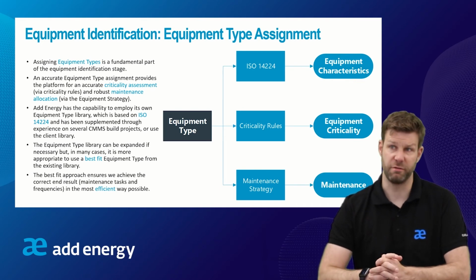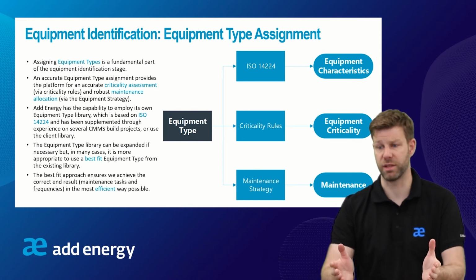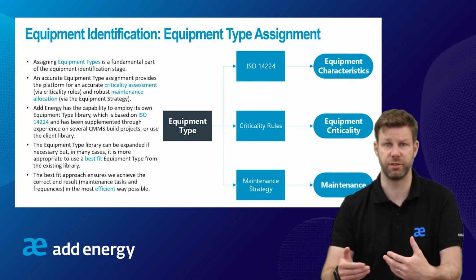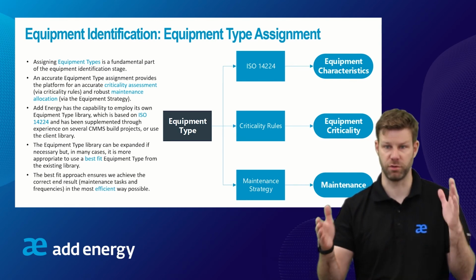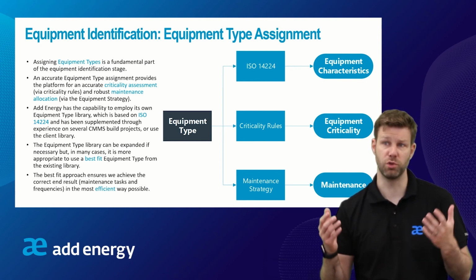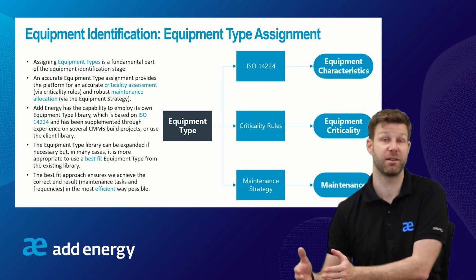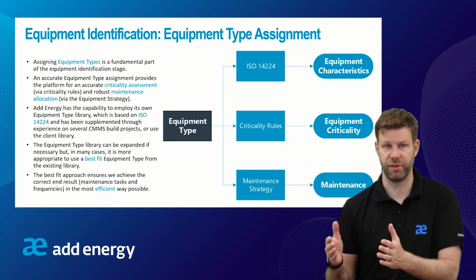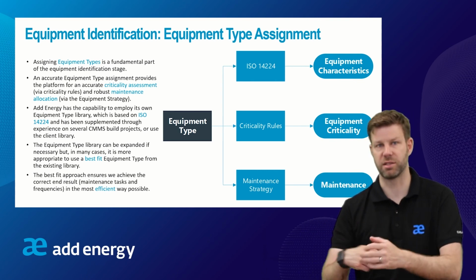Another example would be valving. One of the main things when it comes to the practical application of changing valves out is the face-to-face value from the flanges. It's something that you can capture in your CMS and hold, so when you're ordering the right type of spec of valve, you know the valve will fit in the place it's come out of.